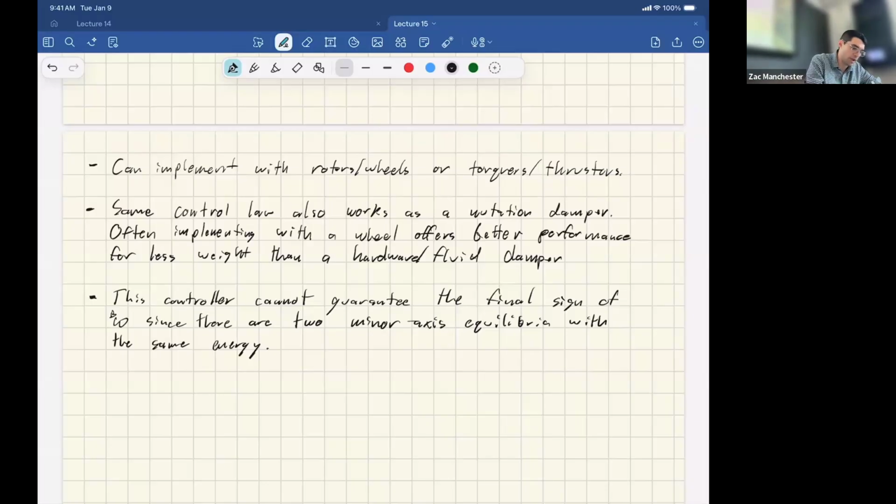So actuator commands being reaction wheel torques, thruster thrusts, I guess forces, etc., and the rho and the tau. Okay, so we'll talk about thrusters first. The gist here is you're never actually going to have three of these things that perfectly align with body axes. Typically you have more than the minimum number for redundancy.